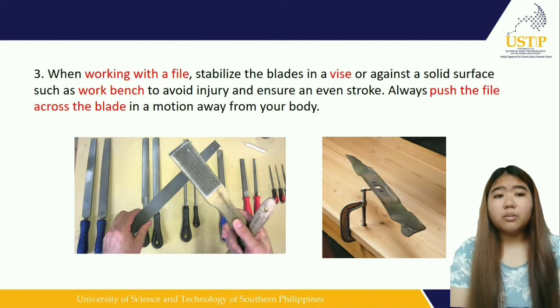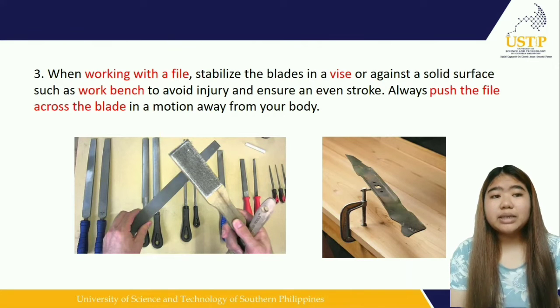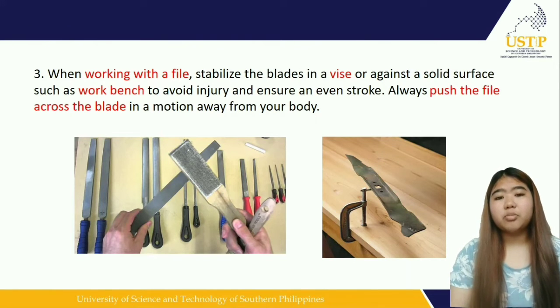Third one, when working with a file, stabilize the blade in a vise or against a solid surface such as a workbench to avoid injury and ensure an even stroke. Always push the file across the blade in a motion away from your body.